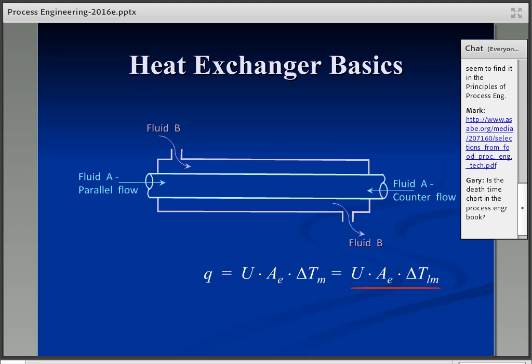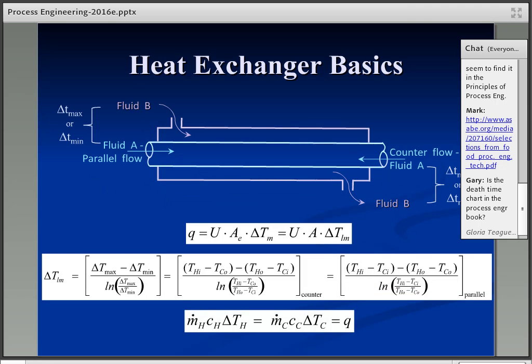I've rewritten the equation now where I've written it as delta T Lm. So you may remember from heat exchangers, that's a log mean temperature difference. Because in basic heat exchangers, a theoretical analysis shows that the correct average is just the log mean average. So you can calculate your average that way, and that equation's been derived for those, and we'll list it here.